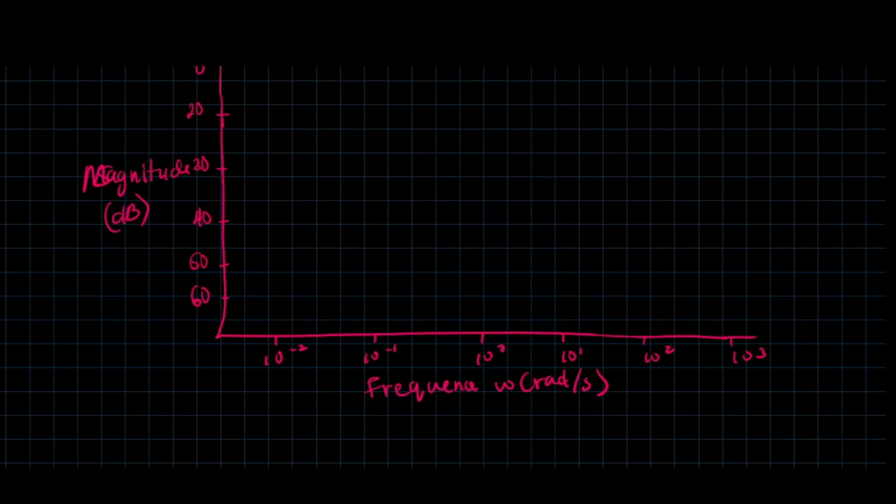So for the first part of the table, at 0.1 break frequency, we had a total slope of minus 20. So around that 0.1 point, which is here, we're going to drop it by 20 decibels.